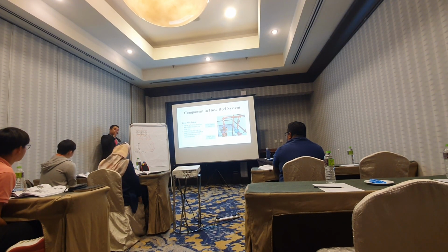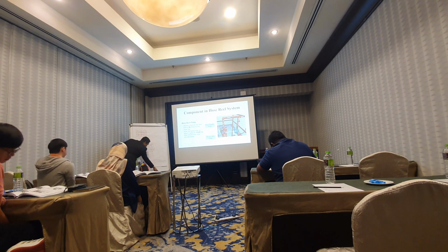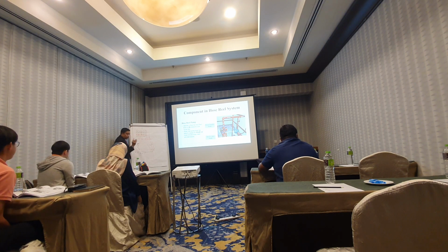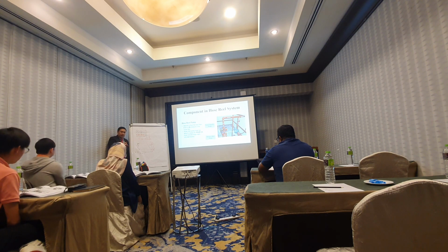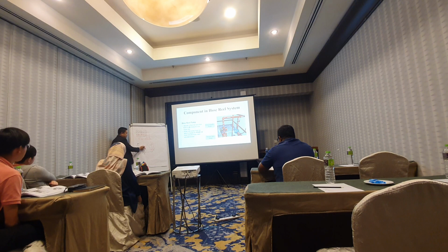Okay, the arrangement of the hose reel location we will look at in a while. I just want to tell you the capacity of the tank for this one, 7,200, is for 4 hose reels, right? If you design the warehouse just now, you said this warehouse has a very hazardous, very high fire load, and you said we need 6 hose reels to operate at one time. So you can upsize the water tank by that calculation.